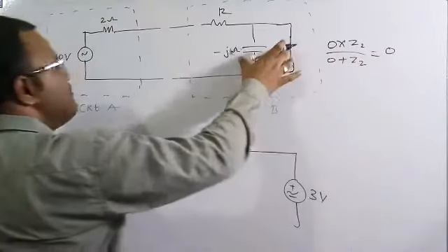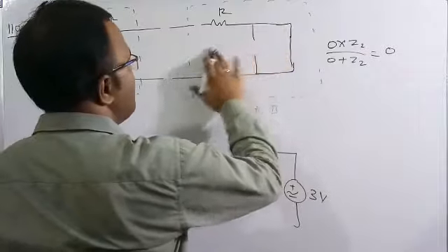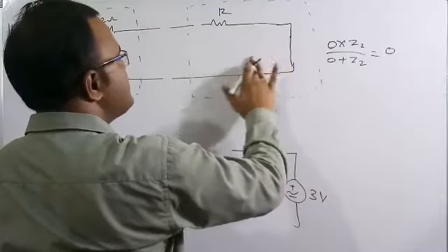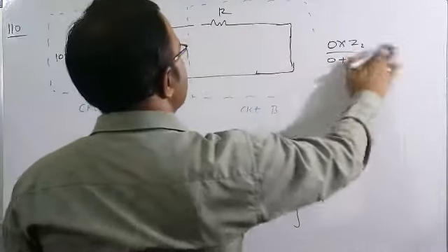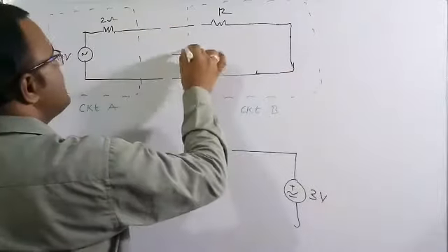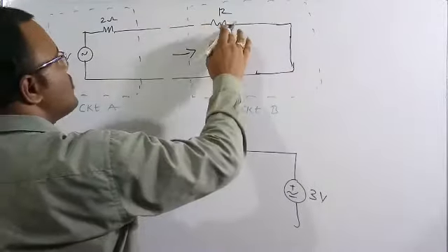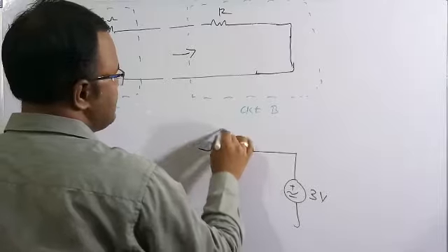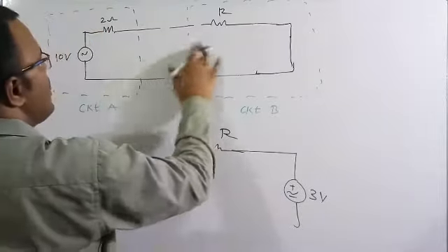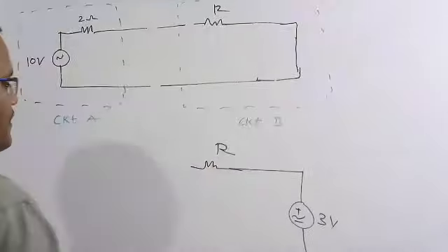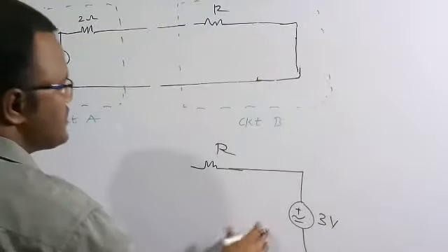So the net impedance of these two parallel combinations will be equal to an ideal conductor, meaning pure resistance equal to 0. So now the Thevenin impedance across these terminals is equal to R. So what I have done is transferred this complex circuit to a simpler circuit.